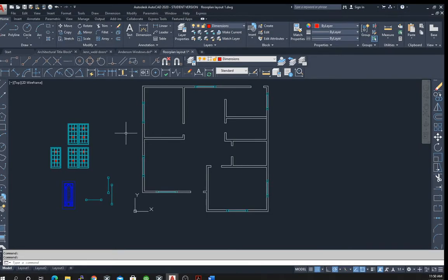We'll come back to AutoCAD. Construction line. So we'll move out here, type 40 feet, use our tracking line, and we of course put that in the wrong layer, but we'll fix that.